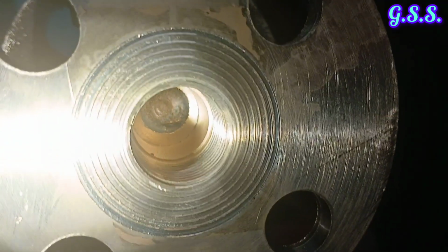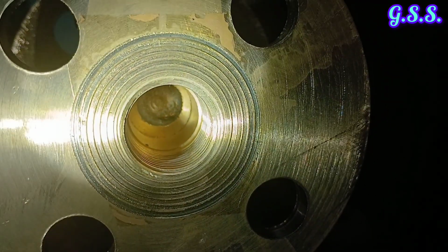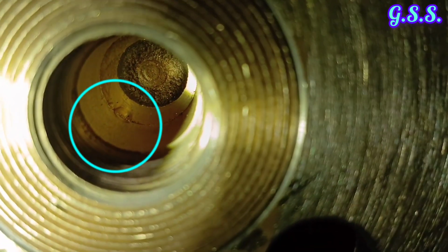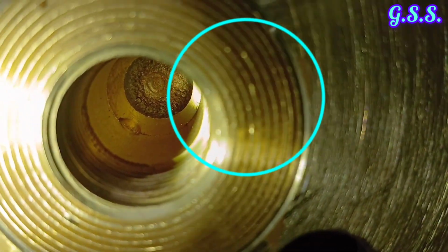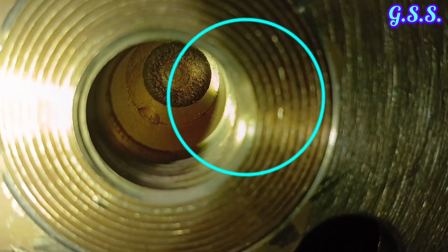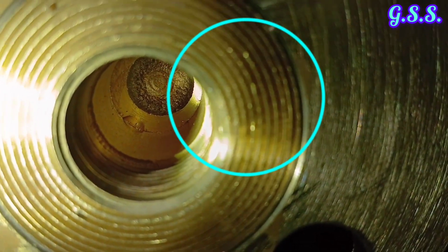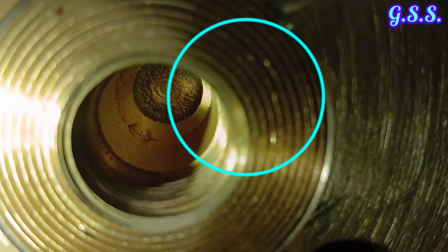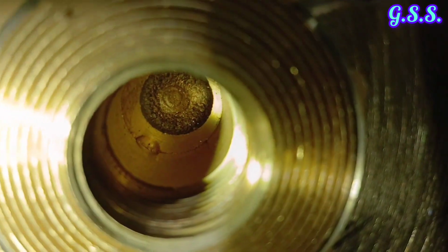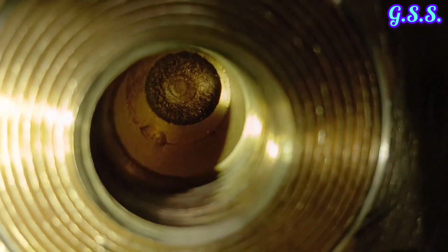During valve testing at valve manufacturer's works, we may get this type of minor leakage through valve seat and this type of water seepage through valve's body. This much of leakage is acceptable as per API 598 and the valve can be treated as per leakage class 4.